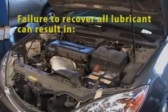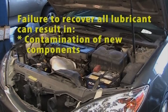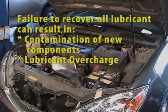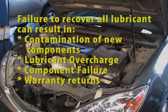Failure to remove remaining lubricant in the system will result in contamination carried forward into the new components and a lubricant overcharge. Doing a complete repair the first time makes happy customers and eliminates warranty comebacks.